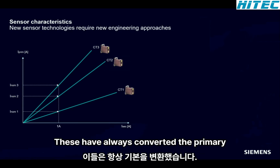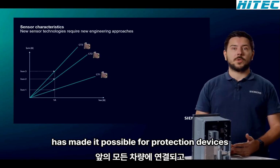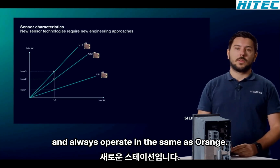These have always converted the primary current to 1 amp or 5 amp secondary current. This standardization has made it possible for protection devices to be connected to basically any current transformer and always operate in the same measuring range.